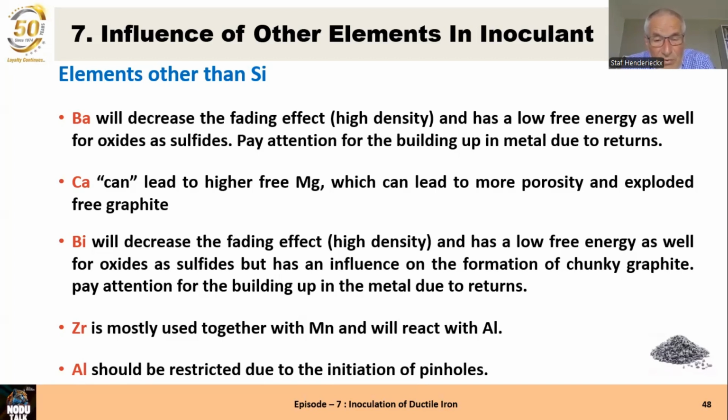Zirconium is mostly used together with manganese, but it will react with aluminium. And aluminium should be restricted due to the initiation of pinholes, especially in the monsoon season, when the humidity in the air is fairly high.